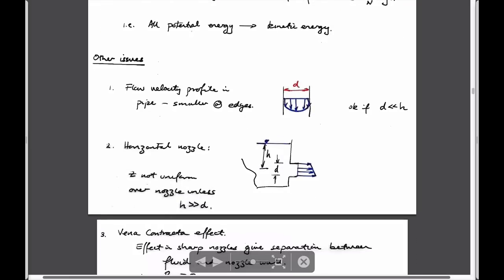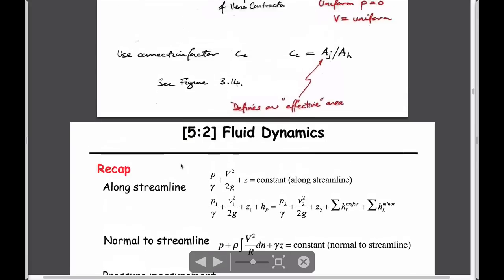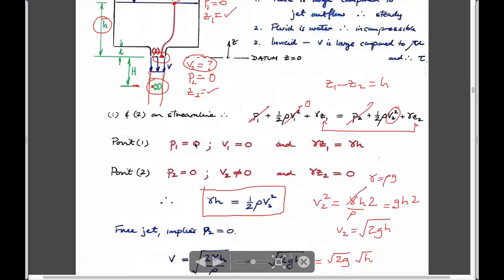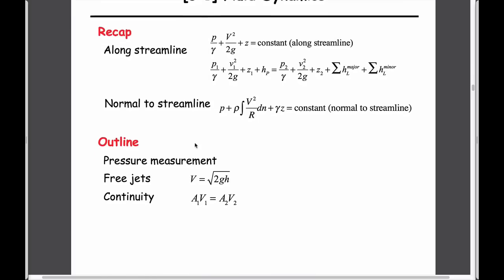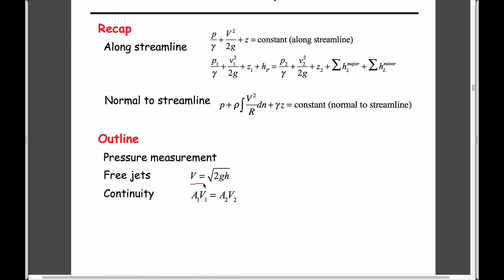And I think that's all we need to talk about. So those are the things we started off with today. I guess we got through them. They're kind of summarized here. The equation of a free jet is relatively straightforward, scaling with square root of 2gh. And the fact that if we only know 4 of our parameters in the Bernoulli equation, and we really want to solve something, we can write continuity, and that takes care of one of the parameters. Okay? Perfect timing. Questions?